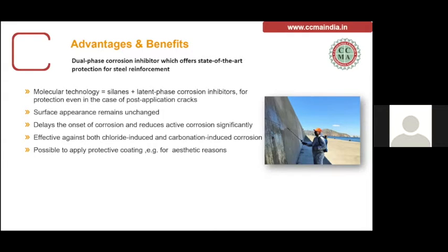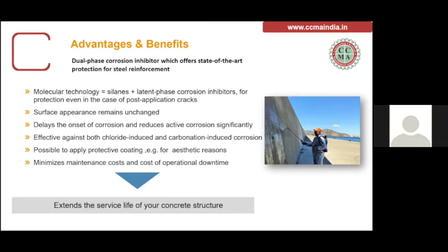Of course, if there is a need for an aesthetic painting over and above, it can be done, because this is entirely migratory and it penetrates inside. So you still have the option of providing decorative paint over that, and it minimizes the maintenance and operational downtime costs. So overall, if you sum it up, it extends the service life of your concrete structure. If I go to the first slide that we were discussing, that's what your repair has to do, or initially during the construction and monitoring phase, if you include certain technologies and systems during your construction, then your service life is automatically extended. So this is what the advantages are.